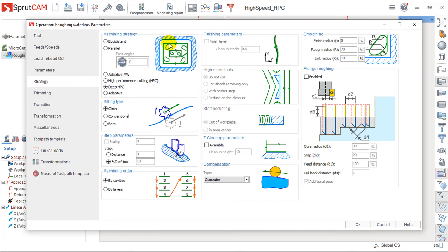We can have maximal cutting depths, and we can go until the full length of the flute or the insert of the tool. So we can have this very interesting toolpath. And the cutting widths, or the lateral increments, should go from 5% to 30% of the tool diameter.